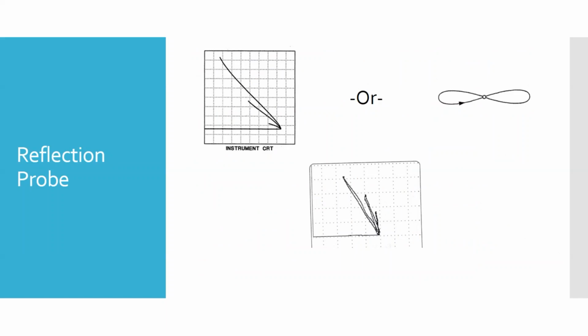So the actual indication, what you're getting, just know it can look different. You can see typically we're putting the origin somewhere around the lower right corner, except if you know you're going to get one of these bow tie ones, you probably don't want to put it right down here, right? If you know you're going to get a bow tie style indication, you probably want to put it more in the middle of the screen. But otherwise, most of the time we want to orient it so that our origin's down here.